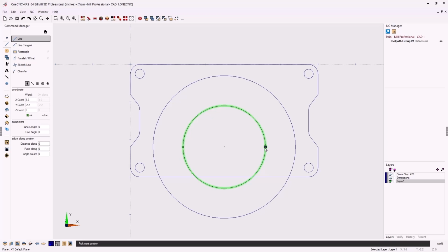So I can left click, pull straight down, and this dimension doesn't have to be critical. I just have to go past that horizontal edge of the boundary. I'm going to left click, now move to the left, left click, and I'm done with that. So I'm going to right click and create this vertical line over on the other side. There's the little symbol telling me that I'm at the quadrant. So I'm going to left click, pull straight down, and when I'm done, right-hand mouse click.